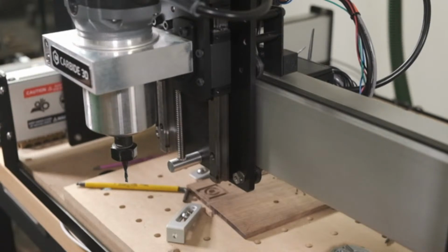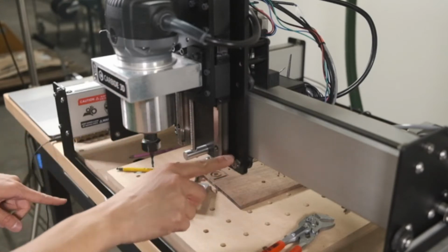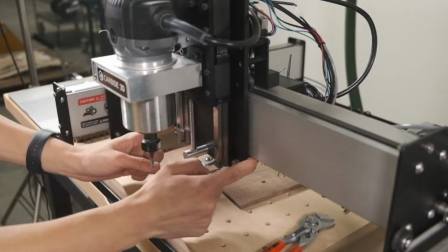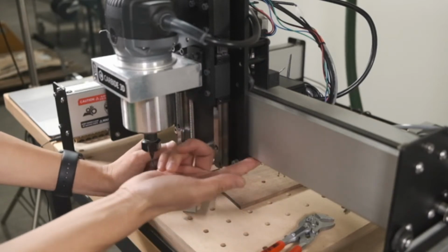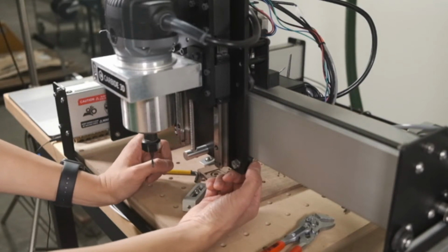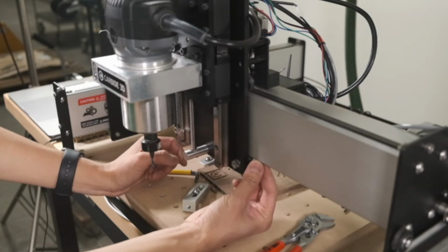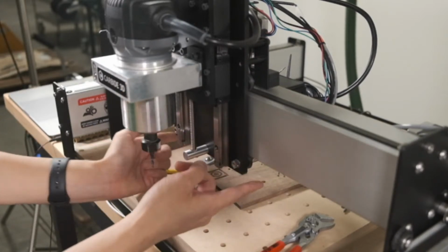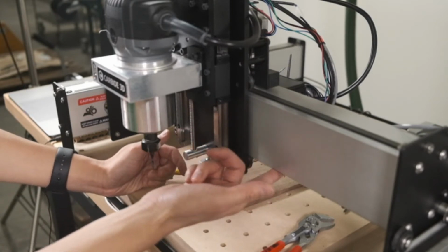So here's why you don't want to just crank these eccentric nuts all the way up and just have the V-wheels crushed against the rails. If you do that, you run the risk of these V-wheels, when your machine is idle or not moving, developing a flat spot. Because it is plastic, they will deform and take a set over time. So you want to keep them pressing against the rails, but not crushed without deforming the plastic. These should roll freely. Also, if you crush these wheels against the rails and they do build up a flat spot, it's going to cause a lot of resistance when you roll.